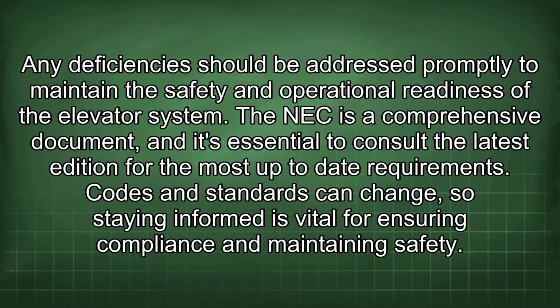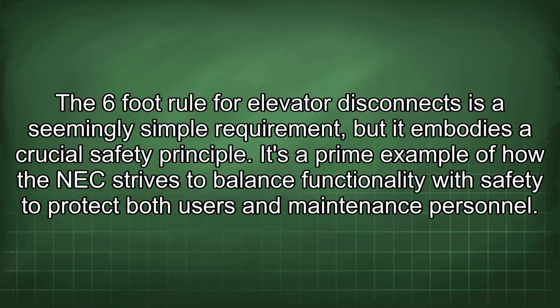The NEC is a comprehensive document, and it's essential to consult the latest edition for the most up-to-date requirements. Codes and standards can change, so staying informed is vital for ensuring compliance and maintaining safety. The 6-foot rule for elevator disconnects is a seemingly simple requirement, but it embodies a crucial safety principle. It's a prime example of how the NEC strives to balance functionality with safety to protect both users and maintenance personnel.